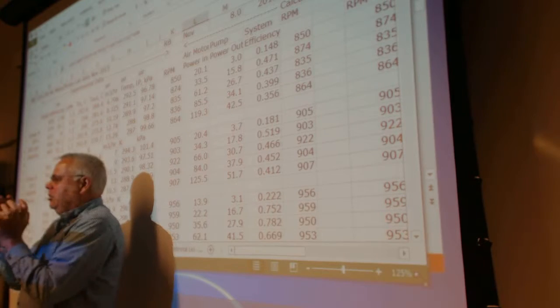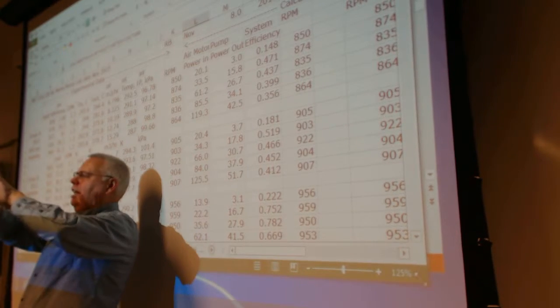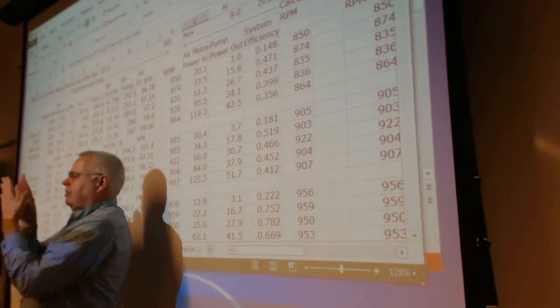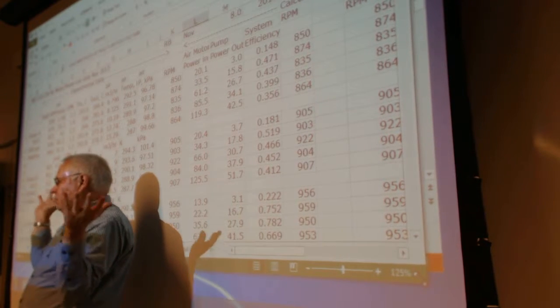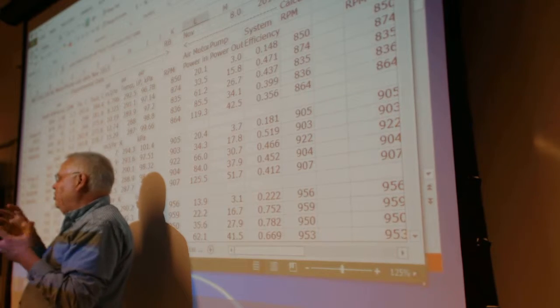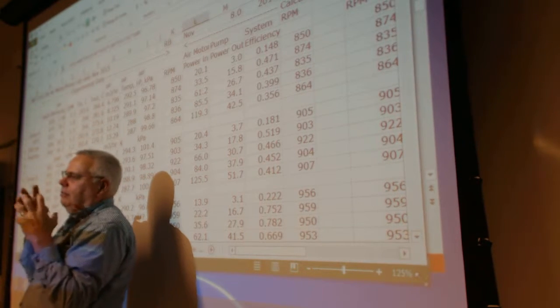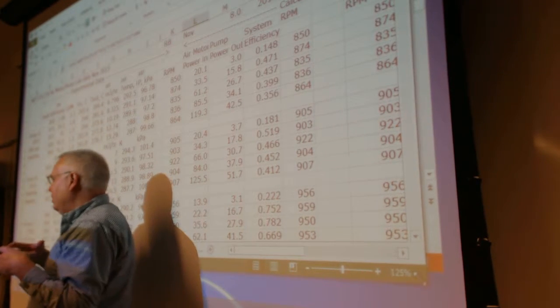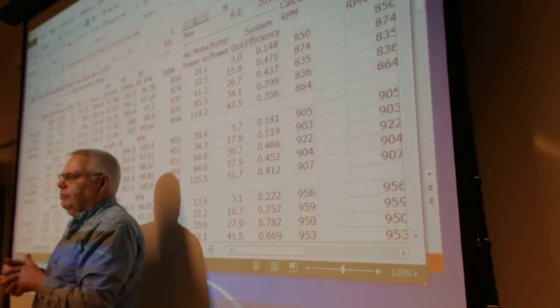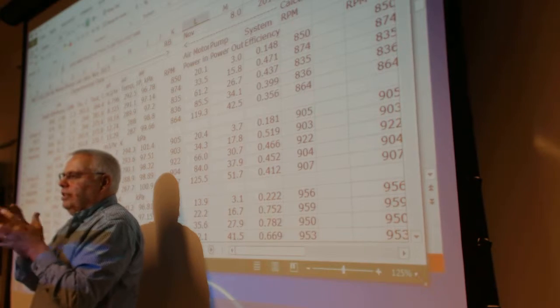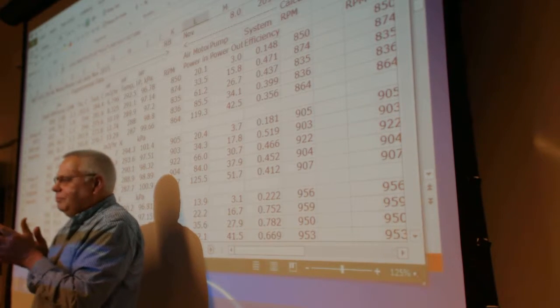You had basically 2 gears meshing like that, but on the 2 faces, there's a seal there. If you put too much pressure on it, and the seal is too tight, then it gets hot and wears out, and then it's not a seal anymore. If it's too loose, it's not a seal anyway. So the seals in pumps, where the motion happens, are usually the failure point.